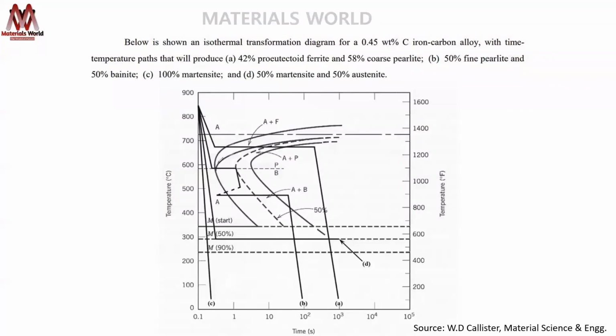As you can see here, see this line. We started the pearlite conversion. 50% austenite is converted to pearlite. Now, if it is passing through this line, even though it's passing through the bainitic region, it will not start bainitic transformation because it is not touching the bainitic transformation. It is touching the start of martensitic, and it is crossing the start of martensitic. Got my point? So if you are passing through this, you will not get bainite, but you can change the route.